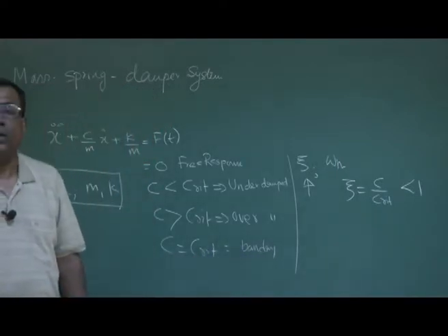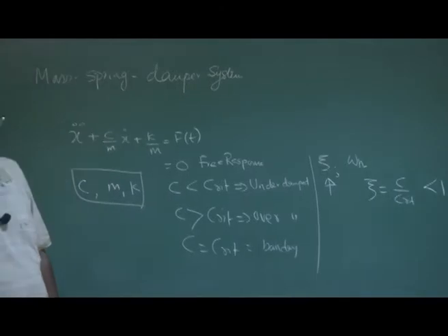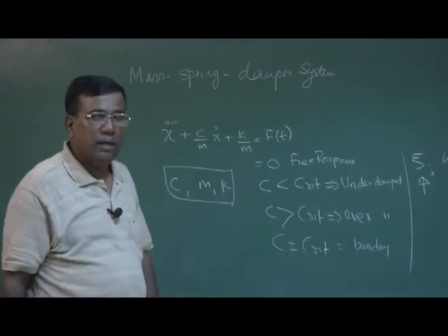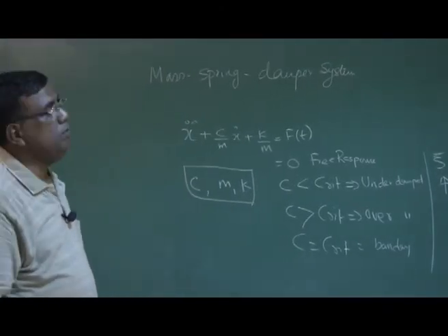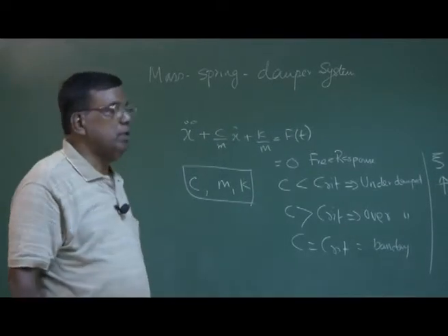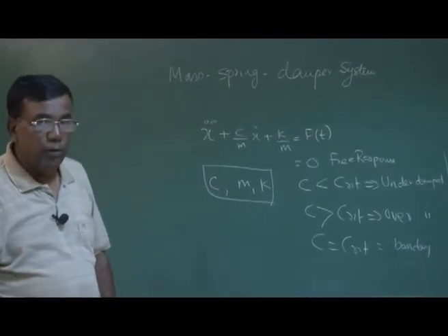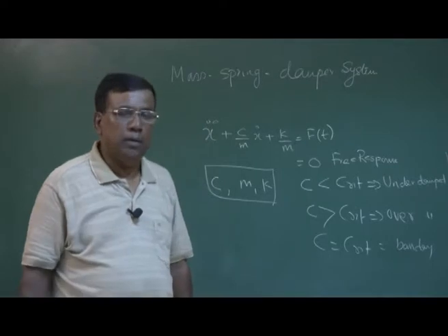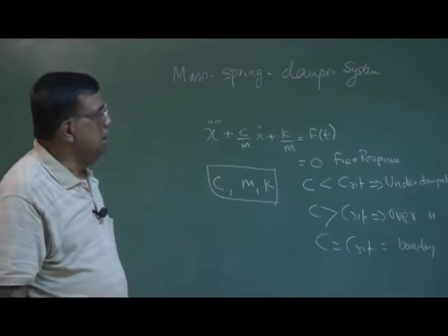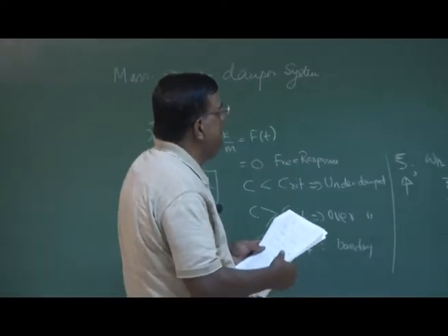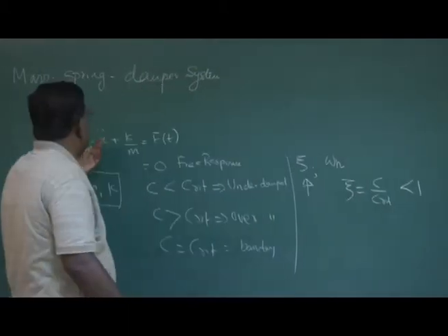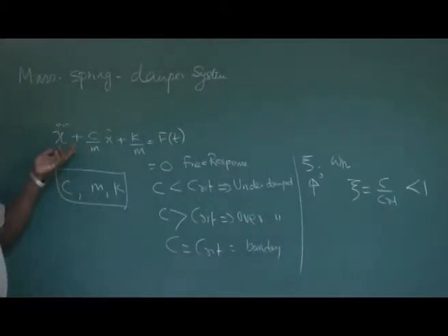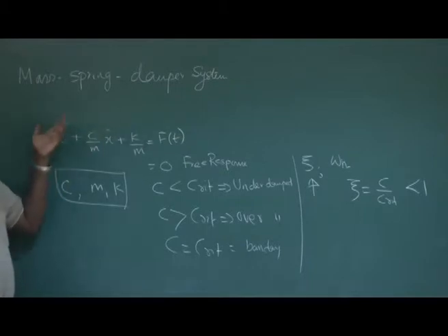It will also be non-oscillatory, but it will return fastest to the equilibrium once the disturbance is withdrawn. We are all talking about the disturbances when you are assuming that there are small disturbances about the equilibrium. And so we realize that this equation, which is the equation of motion for a mass spring damper system, is how its x coordinate is changing, how this gentleman is moving in x direction.